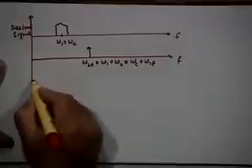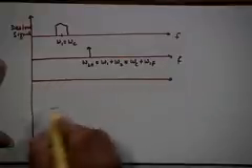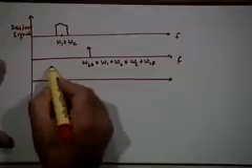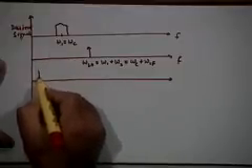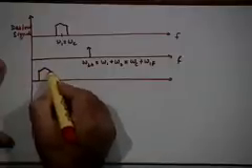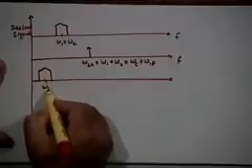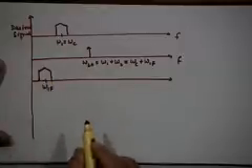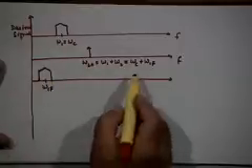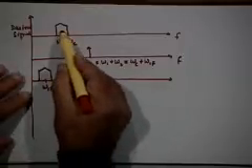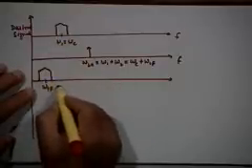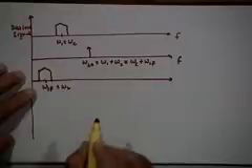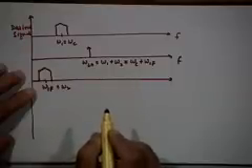And after the mixing of these two, this signal will be translated to omega IF, which is typically a lower frequency than the incoming carrier frequency. So this message signal is put back to omega IF. So this is your omega 2. Omega 2 is now equal to omega IF.